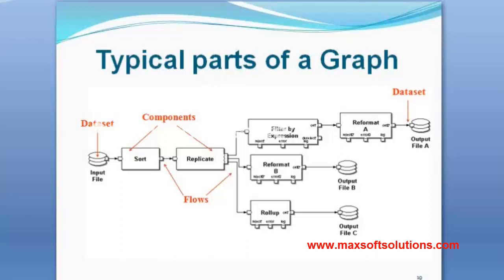The components which have a different number of ports will have a count parameter associated with them. Join has a count parameter so that we can increase the number of input ports. If you increase the count to 5, then join can accept 5 different inputs. The default value for count is 2, as you have probably seen in the join component.